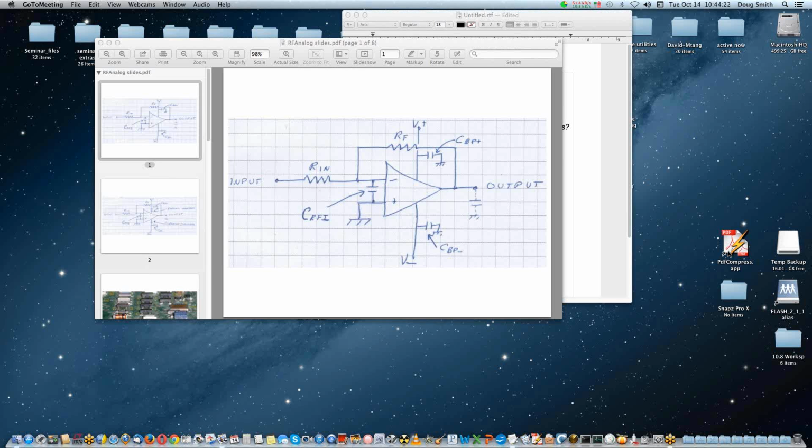Tom? Yeah, and I'd say, again, the punchline to every question about EMC, the issue is it depends, but it does, because in the case of an op amp, if there's a specific area on a circuit board that is sensitive to some interference that you're aware of, one attempt I've seen done successfully is to get a specific board level shield around that device.